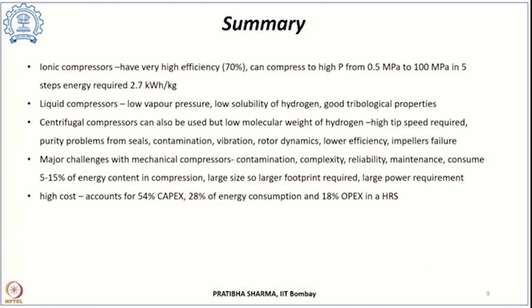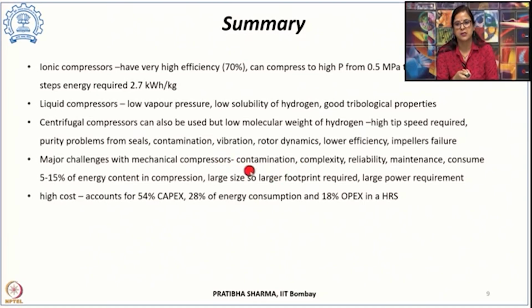So, we have seen that the major challenges with mechanical compressors are that there could be contamination of the gas because of the moving parts, because of the lubricating oil used, and because of the seal materials used in the seals. The design of these compressors is complex. There are challenges associated with their reliability. Since they have moving parts, there is a cost associated with maintenance, and regular maintenance is required. Monitoring of these devices for failure is required.